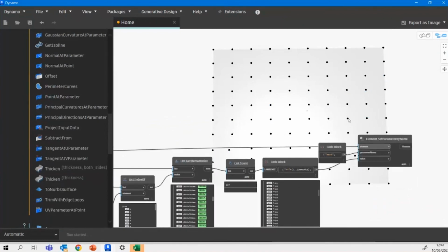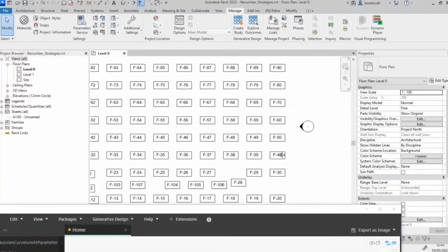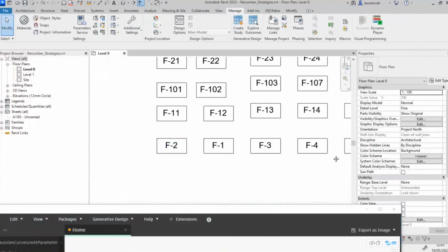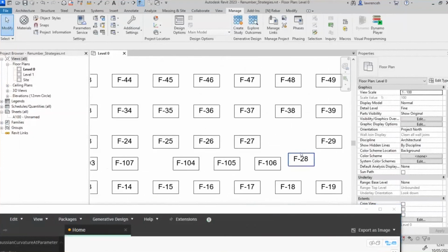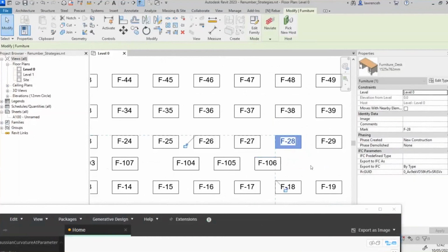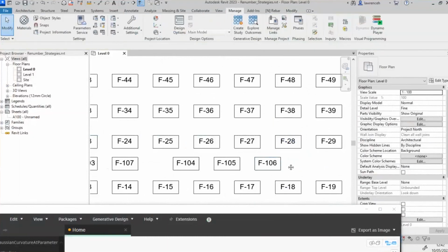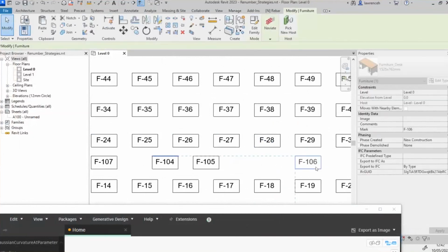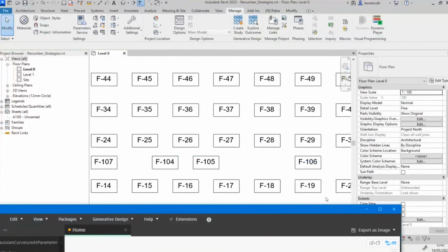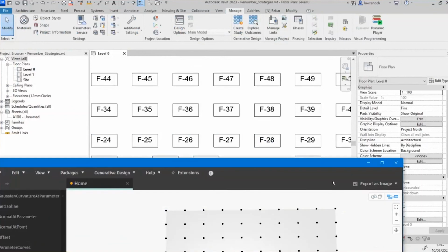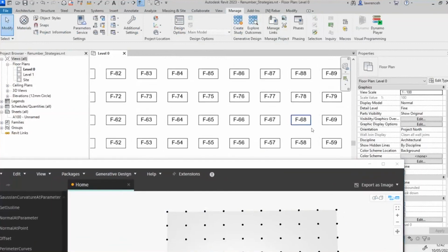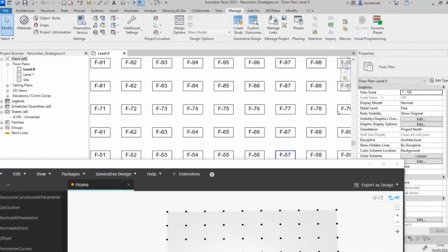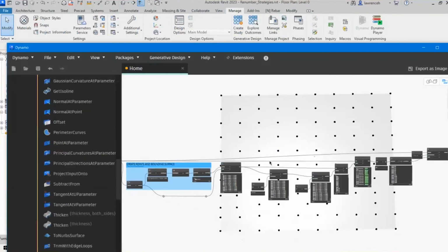Okay, we can see we get a slight delay there while Dynamo does its magic. And now if we take a look at the numbering system, we can now see they're all very neatly in order. Now, just to show you some bits and pieces here, if I get that piece of furniture in there and shift it round, and then get that one over there and place that in a different location, that would cause Dynamo to reevaluate all of those positions and renumber them accordingly. So, you've just seen there how to build up a relatively simple script from first principles.